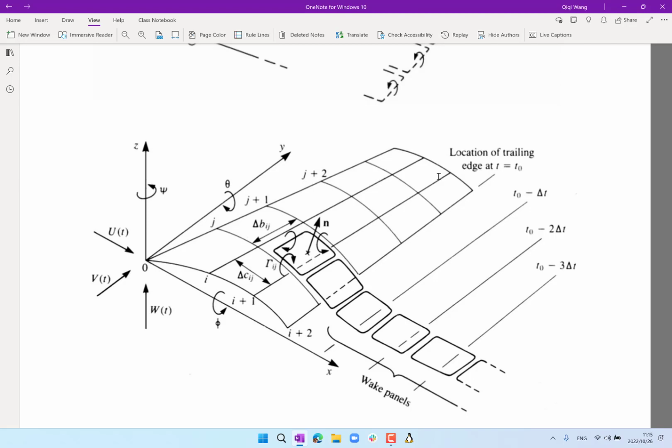So these kinds of things can be done not only for steady state airplane flight, but for unsteady maneuvers. So this vortex lattice method, being able to track how these rings move and deform as a function of time, is superior to the lifting line method, especially when the loading is high and when you have unsteady aerodynamics. All right, questions?